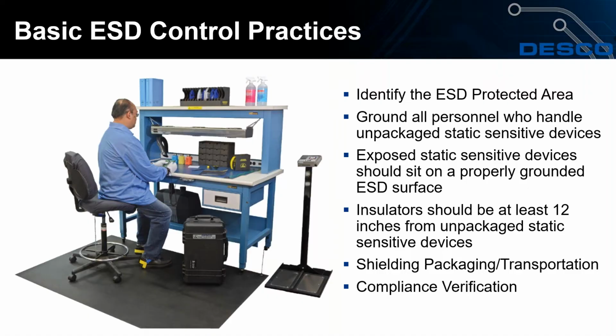And then compliance verification. Once I have all the equipment and materials I need in place to control static electricity, I need to test those periodically to make sure they're in compliance. I need to test my wrist strap every day, or my footwear. I need to test my ESD work surface, my flooring, my chairs, my carts, things like that. I can't just rely that those things are always going to be good. So I need regular compliance verification for those.